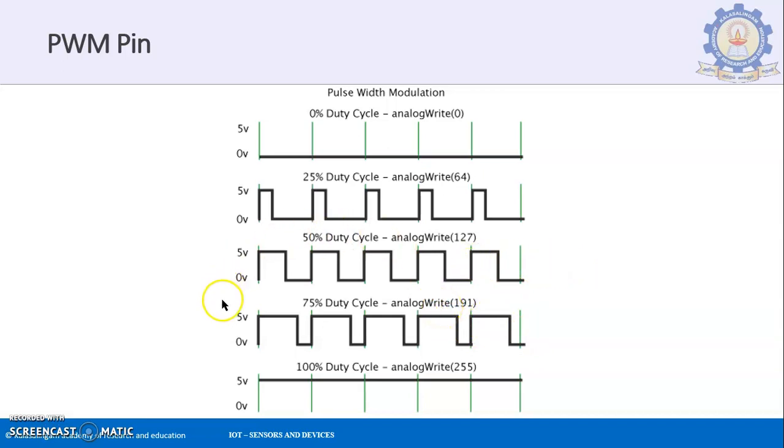Okay. And lastly, we saw that when 100% duty cycle is available, what does it mean? It means that the signal is a DC signal over here, as in the case of 0%. Here 100% means 100% of the time it is on, which means 100 minus 100 is 0%, it is off. So it is entirely a DC signal in which the LED is at maximum brightness, and that analog bright value is equal to 255 over here.